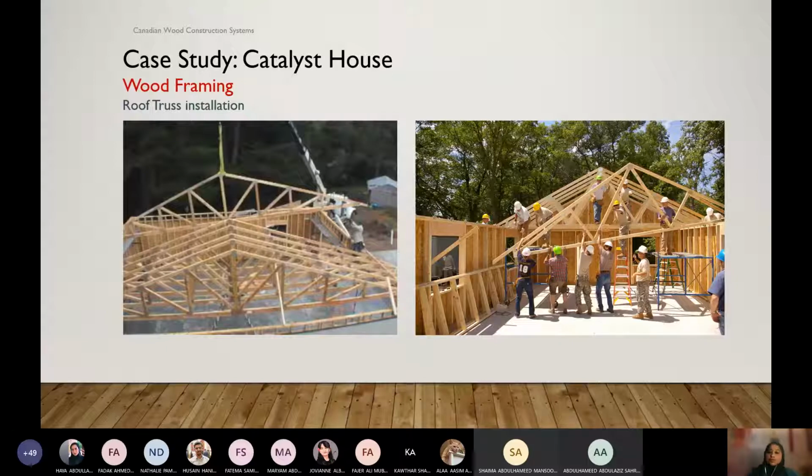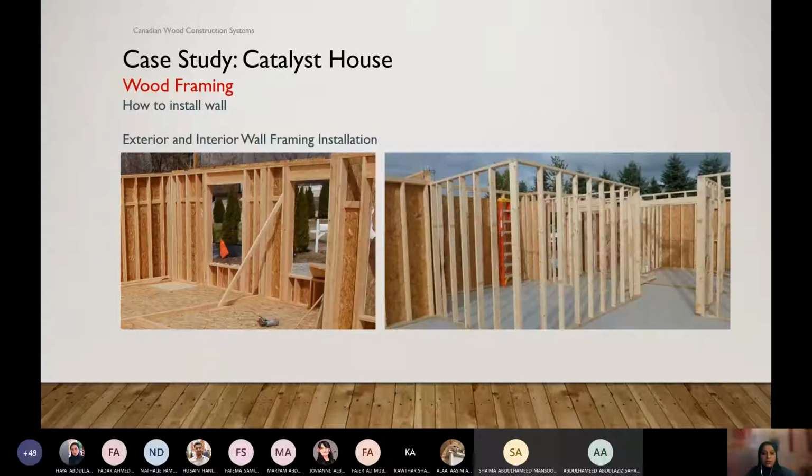One thing I need to mention here also: on the floor, on top of the framing, we put those wood panels. The same way, outside of our wall, this vertical stud framing, we also use those panels, as you can see here. Those panels are the same materials, either plywood or OSB, and they also come in the same size, 4 feet by 8 feet.